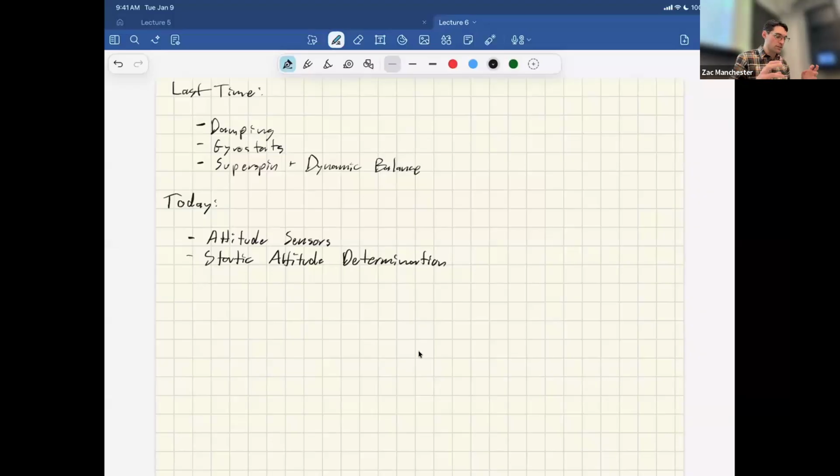So that's what we call static, as opposed to dynamic, which means you're computing maybe not just the attitude, but also the angular rates. You're using a gyro and a dynamics model potentially, in a recursive filter style way in an online setting, that includes not just the instantaneous measurement but some notion of the measurement history and the dynamics, right? And to foreshadow, that's going to be some sort of Kalman filter thing. So here's the instantaneous one-shot version, and after this we're going to get into the more continuous in time dynamic version. But for now, we're going to start with the simplest possible case.